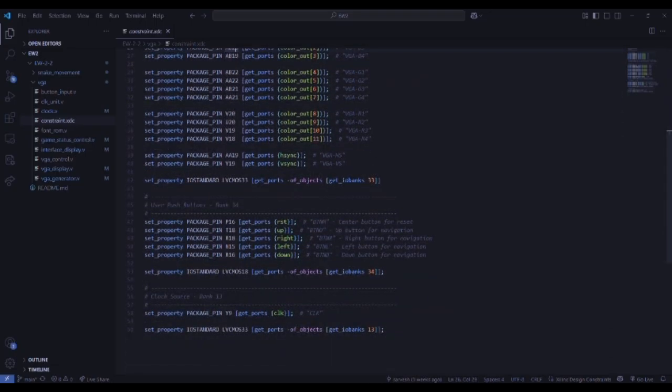And this is for the reset, up, right, left, down buttons. For these pins, we refer to the official documentation of the ZDD board, the Zynq Evaluation and Development hardware user's guide. In this we can see all the particular pins that we have to use. Over here we can see the pin numbers, the ZYNQ pins, and what each pin does. This is the VGA port, which gets connected to our VGA display. For this we have the ZYNQ pins for red video, green video, blue video, and majorly the horizontal sync and vertical sync, which I explained were the most crucial part of our VGA interface.